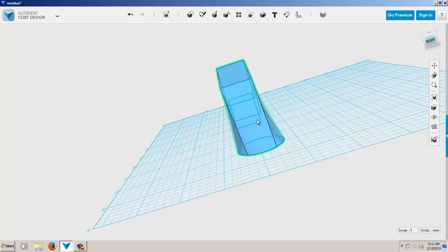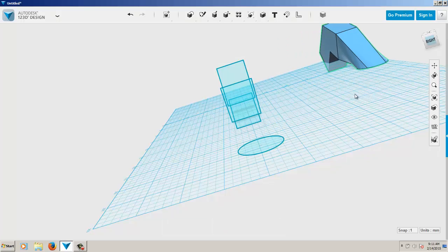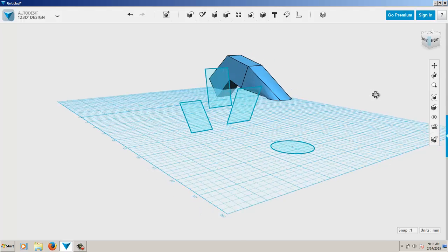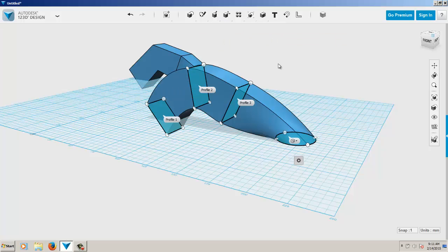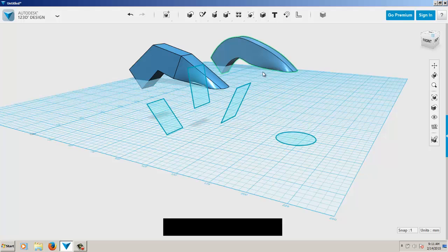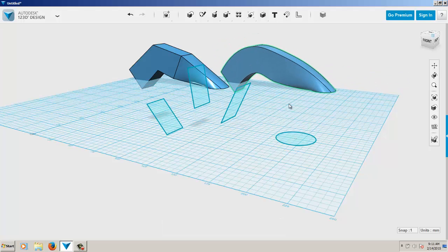And we'll pull that one out of the way, slide it over here, and I will go ahead and show you how the transitions are more smooth as you see all these arcs and points, if you do it all from selecting them to begin with. So I select my profile using the shift key. I select all the profiles consecutively, and then jump up here, grab my loft profile, and you notice the difference. It's a whole different part.